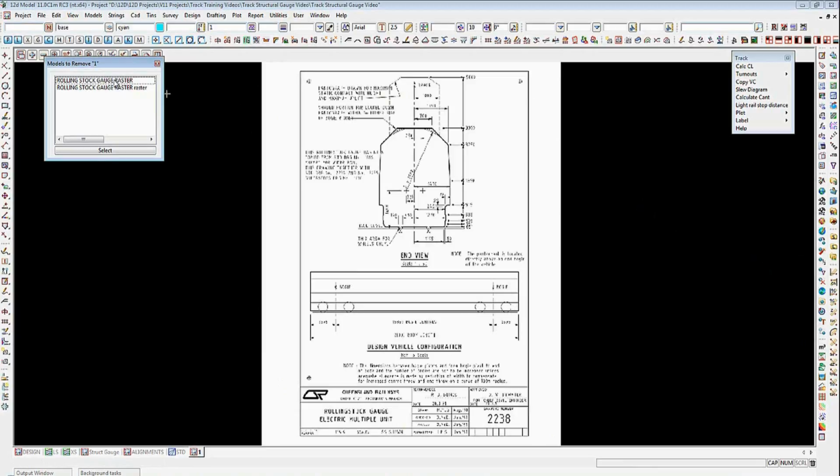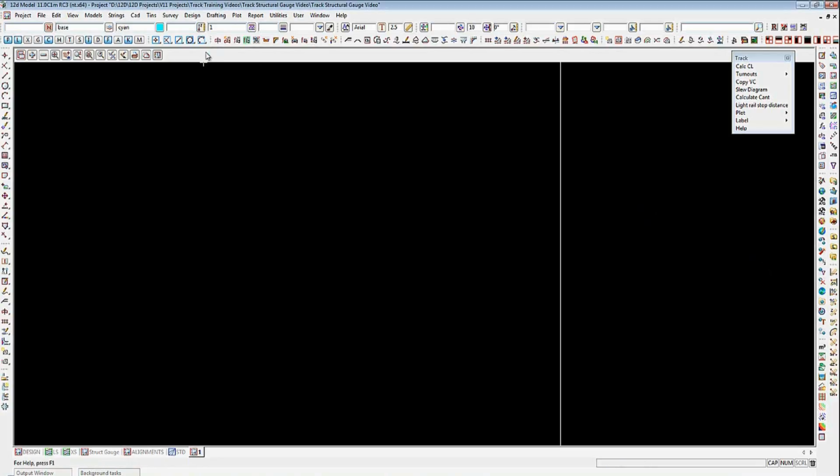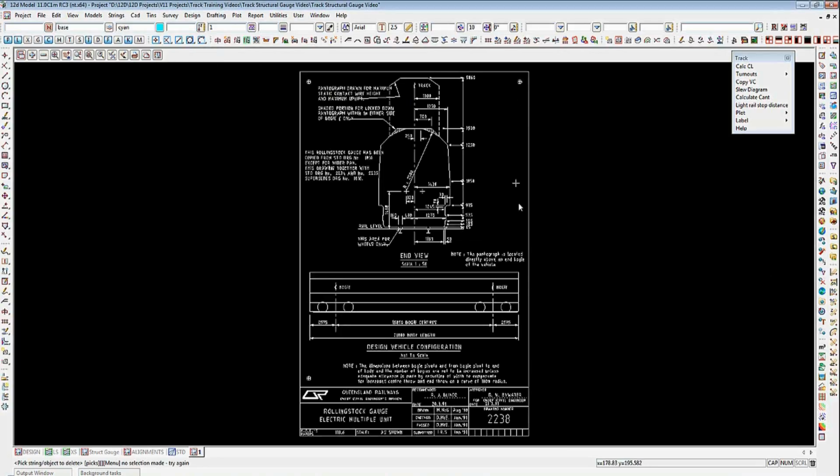Now, of course, not all PDF documents do have vector information in them, but you'll see here that if I go and remove the raster image here and do a redraw, we've actually managed to pick out of this those elements that were in that data set as raster. Now, if you have extracted raster from it, that really means that the original image file is no longer needed, and that could then just be deleted, and we would work with this vectorized bit of data.